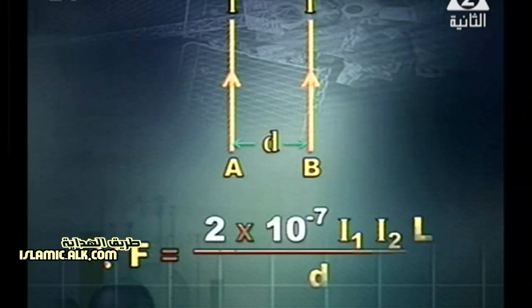Since the force is determined from the expression F is equal to 2 times 10 to the power of negative 7, I1, I2, L over D. This is the expression that determines the size of the force.